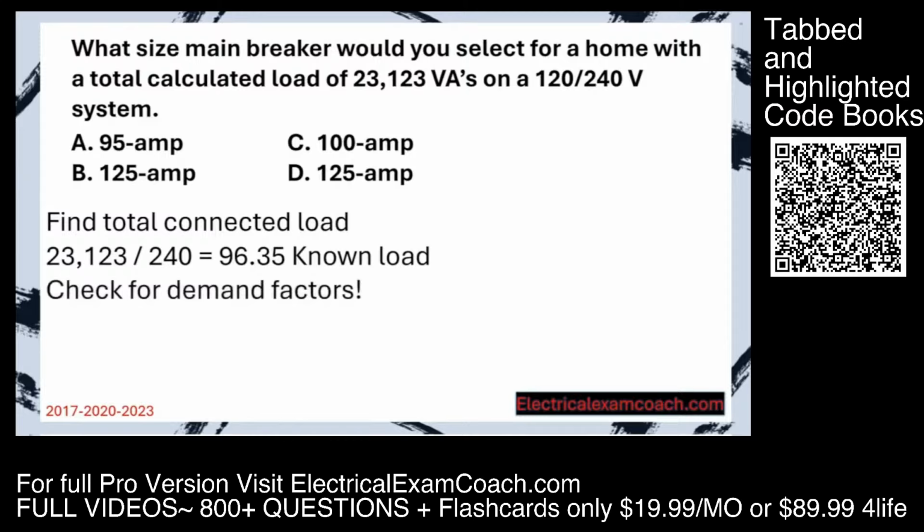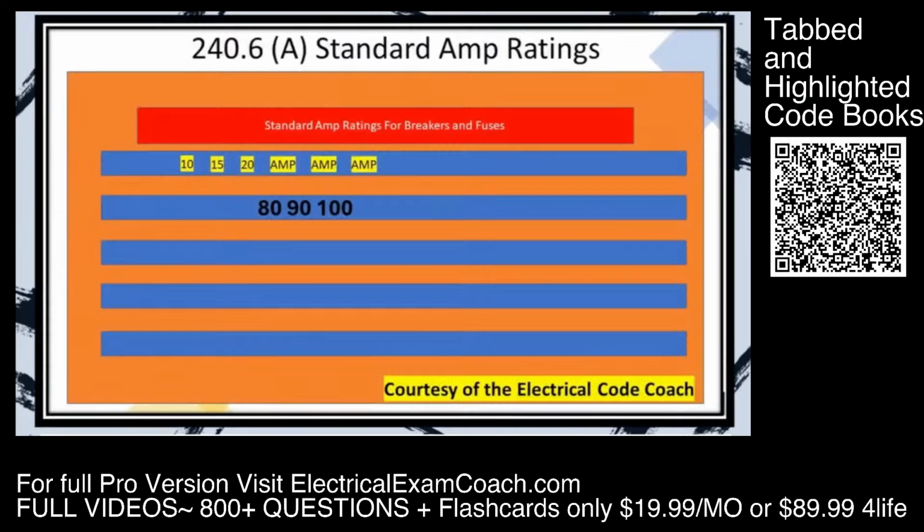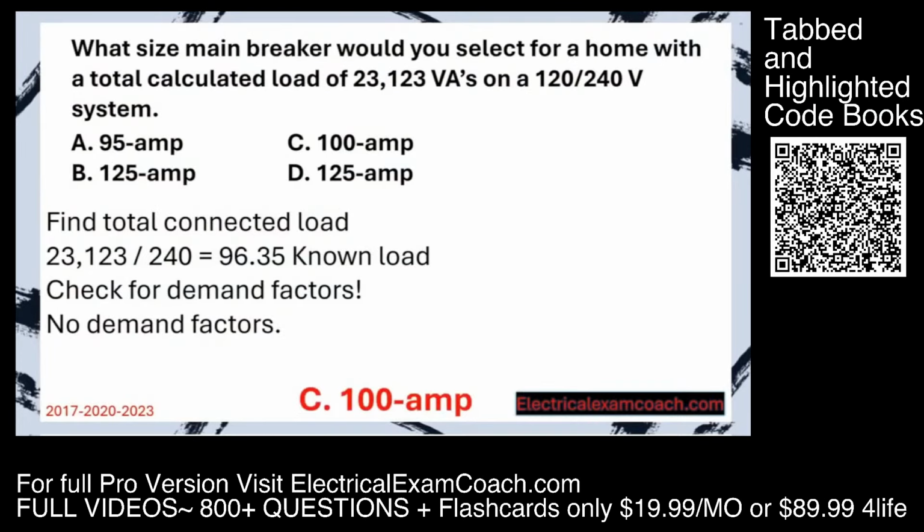Now we check for demand factors. Because this load calculation was already performed, there are no more demand factors to do. They were done along the way, right? We would have performed our range demand factor, our dryer demand factor, and then now we have this total lump sum of 23,123. So all we have to do is divide by 240, and there are no demand factors. Now that we have it, we go to 240.6(A), and we choose the next size up. And in this case is going to be a 100. Great job.